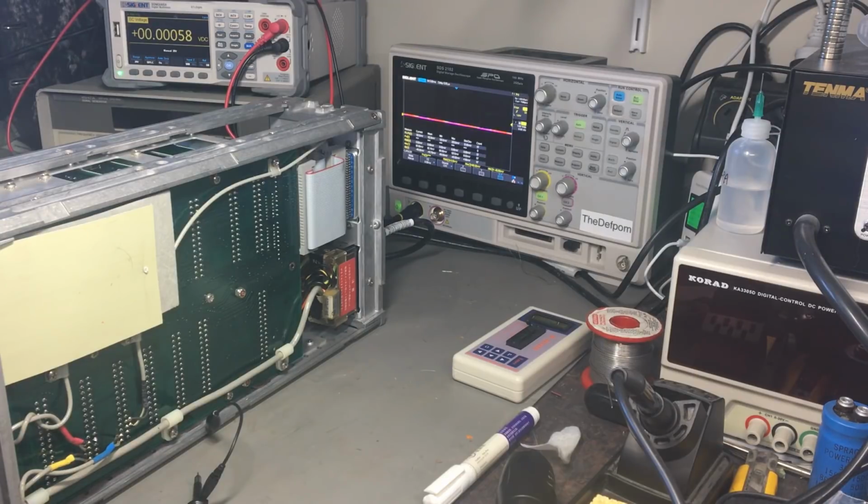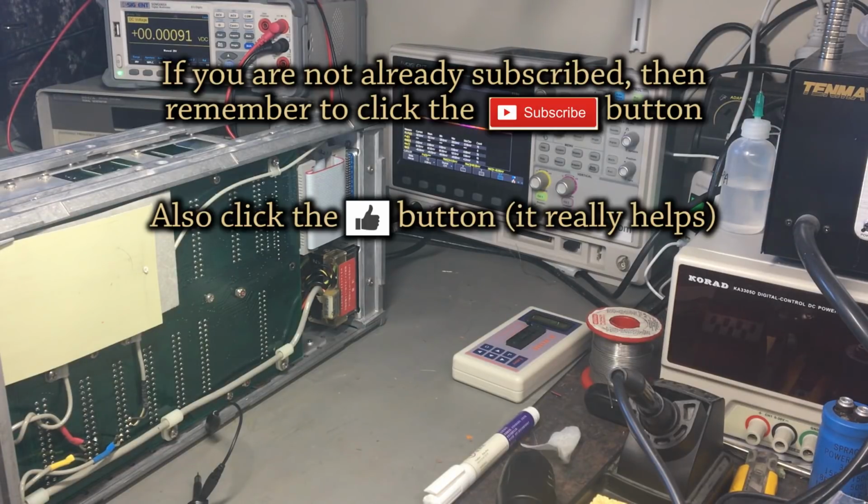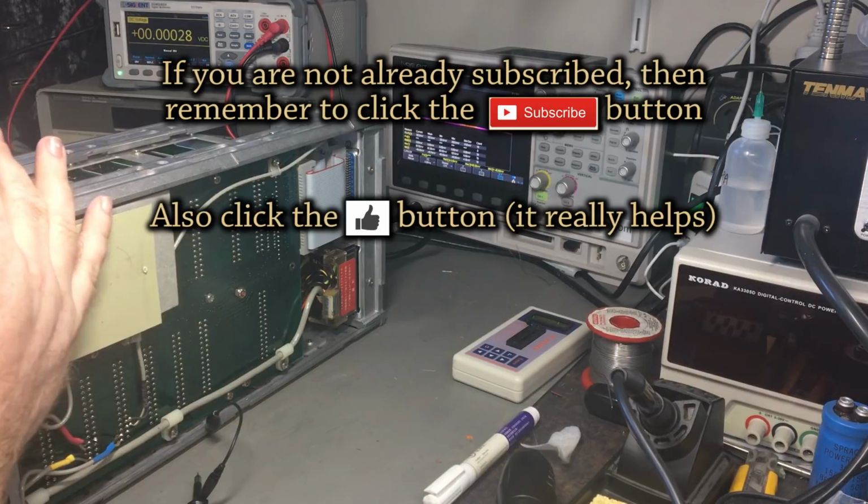Protective diode check, apparently. Right. Remove the front panel from the unit. Oh god. Unsolder the four protective diodes connected to the low terminals. Really? There's diodes in there? I didn't see any.